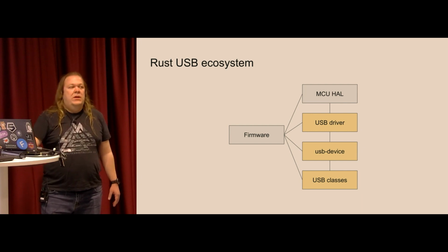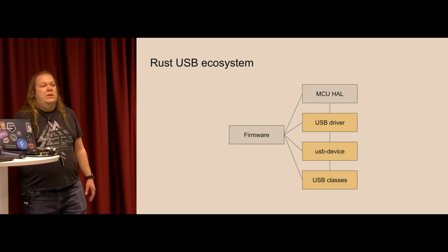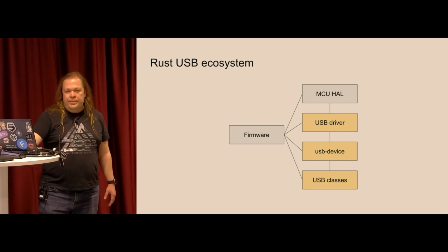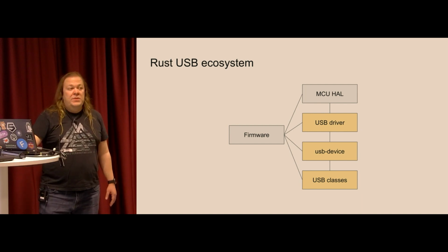USB drivers are MCU-specific components which know how to communicate to a specific USB peripheral and how to implement different types of endpoint transactions. And then USB classes know nothing about hardware. Instead, they know which descriptors to present and how many endpoints they need, how to translate data sent to these endpoints into something useful.